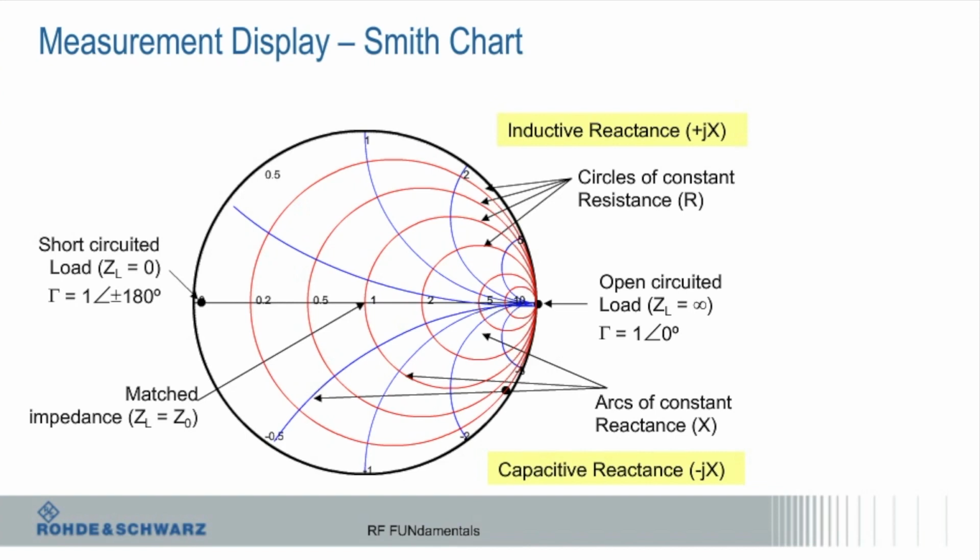So you make it something close to that, and then you measure the hell out of it, right? And you get some really accurate data. So when you send in your cal kit to get it calibrated, they're really, really accurately measuring what that thing is over frequency. So when you do the calibration, it isn't that it says, oh, that's a perfect short, and I get a reflection coefficient of 1 and a phase of 180 from DC to daylight. It actually has measured data on it. So when it does the calibration, it's going to say, I put that on there, and I measure something, and after I measure it, what do I get? I know what the load is. The load is this data file, and I measure what's in between, and that generates my cal coefficients.